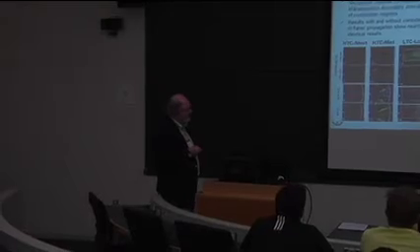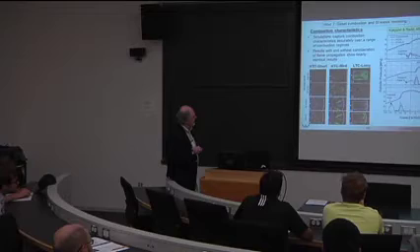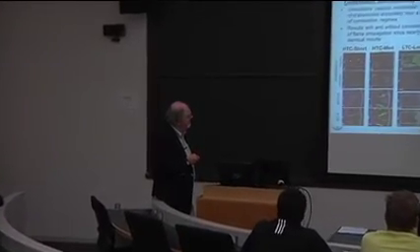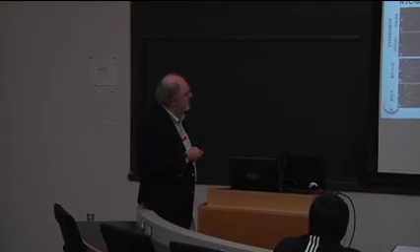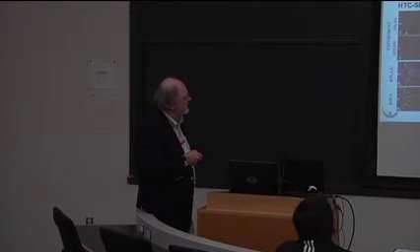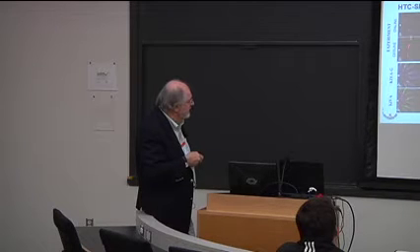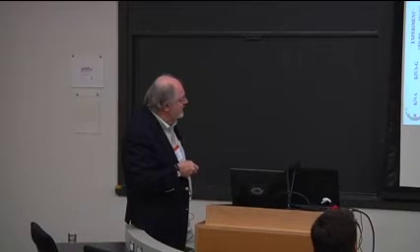There are two pictures showing you the OH distribution, the hydroxyl radical distribution in the engine. It's difficult to see, but if you look carefully, you can see that this OH is confined to a region around the jet in the case of the short high temperature combustion regime because of the existence of a diffusion flame. They're shown here at 6 degrees, 10 degrees, and 14 degrees. I'm looking here just for this case at 6 degrees after top dead center. Down here are the corresponding simulations.